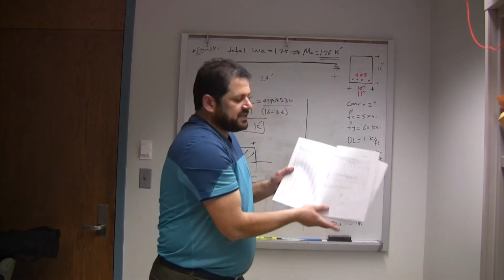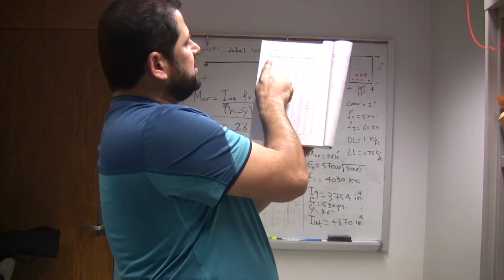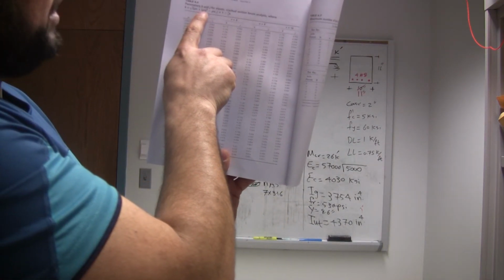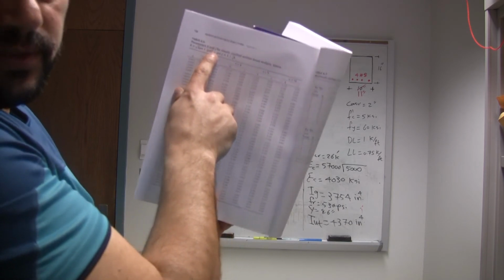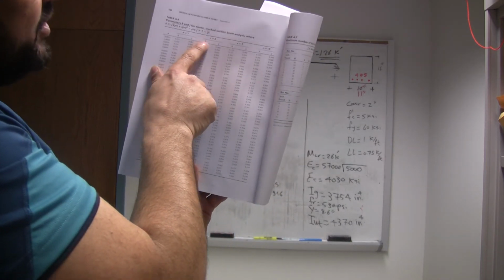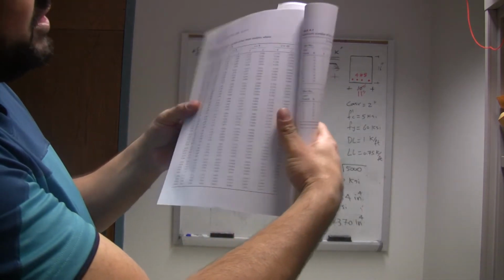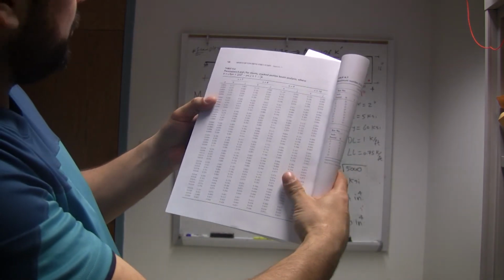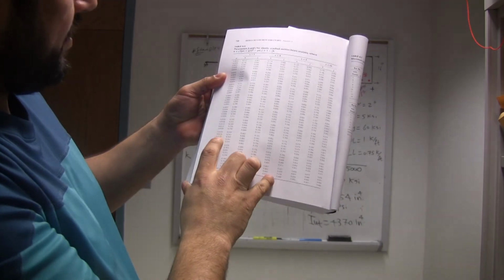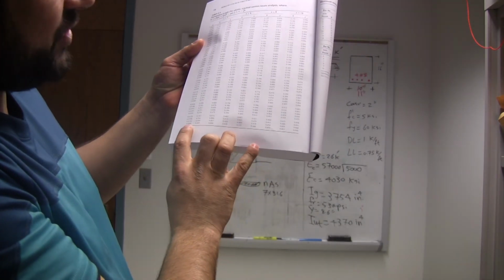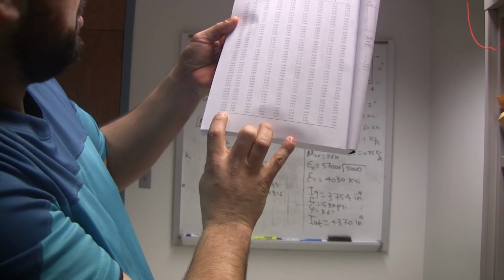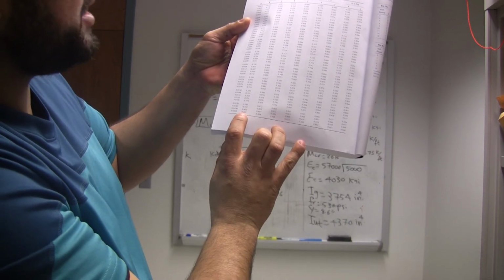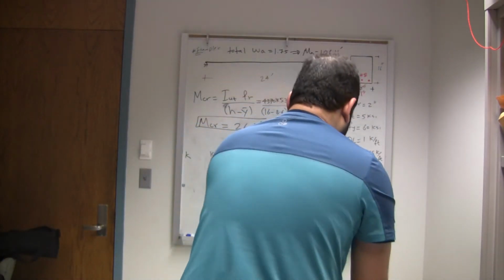Here, in table A6 in the appendix. Okay, this is the formula for K: K equals square root of 2 rho n plus rho n squared, minus rho n outside the square root. And this is J if you want. So our n is almost 7, and rho is almost 0.02, 0.021. So K is 0.407.